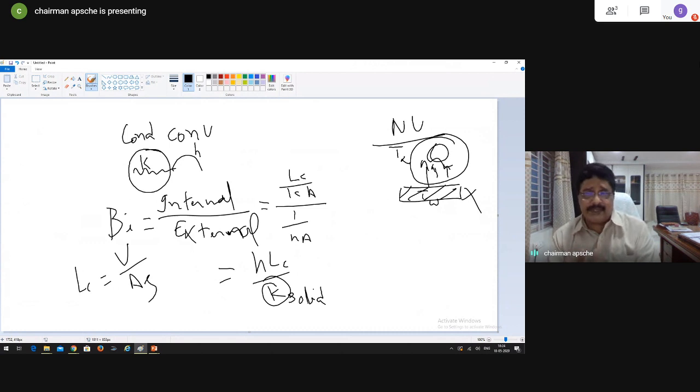So, from case to case, we also discussed viscous fluids. By virtue of the viscosity, the resistance offered to the molecular movement will not be very free. And in that case, it is not very conducive for convection heat transfer to take place. So when it is not conducive for convection heat transfer, convection resistance obviously should be high. So, summarizing everything, Nusselt's number compares the conduction resistance and convection resistance within the fluid itself.